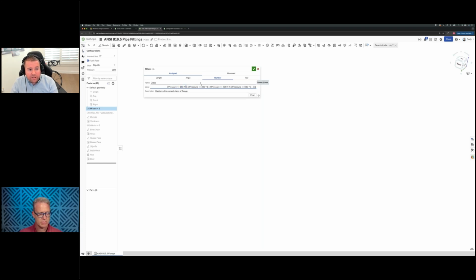If the pressure is less than 300, it's class 1. If the pressure is less than 400, it's class 2. If it's less than 600, it's class 3. And if it's over 600, it's class 4. Now that's just defining that this class number is driven by a pressure rating. And so when the user types in a pressure rating, it's going to automatically assign to them a class number.